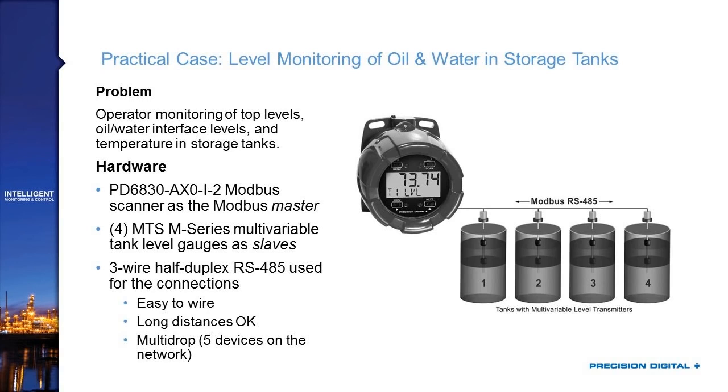But oil and water do get mixed, and essentially if you allow them to settle, they separate. And so in this application, what they're looking to do is use some kind of mix of transmitters to be able to get out the temperature, that interface level, and the top level in their tank.